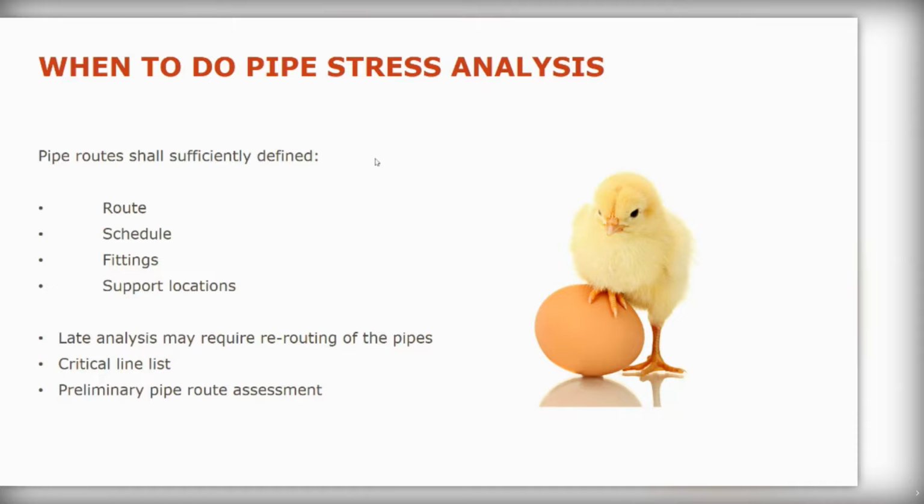That can often be done early in the project without all the paperwork, just the pipe stress engineer talking directly to the designer in the 3D model, working out something that has a very low risk, and then they leave it. They will pick it up when they do a formal pipe stress analysis of the whole run, and it will be covered off then. So again, you can be very targeted about when you use pipe stress analysis at an early stage in the project. That way you will de-risk it at a minimal cost upfront.